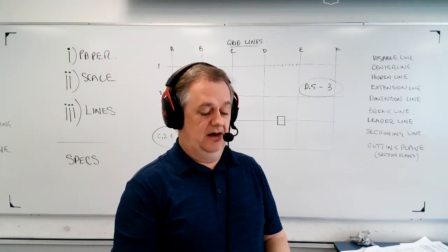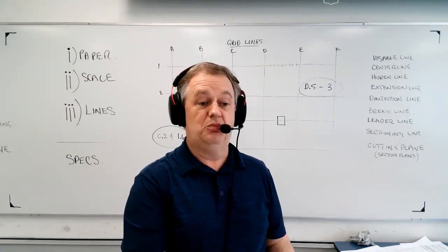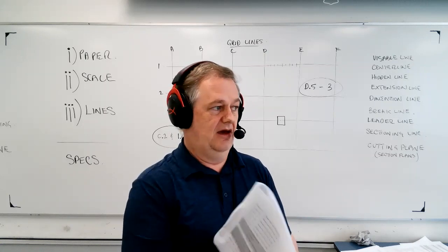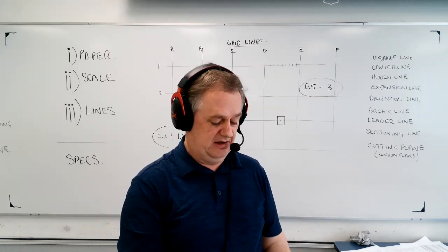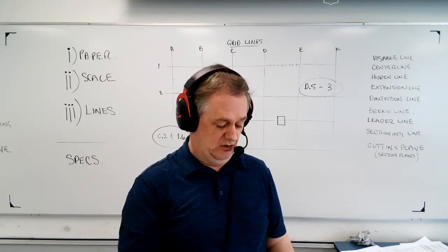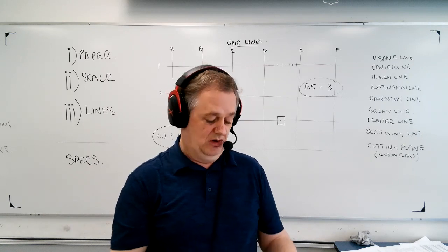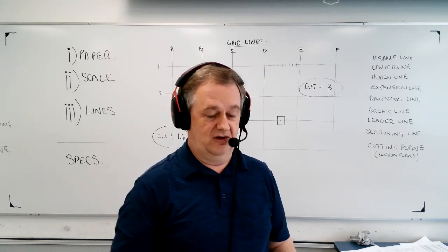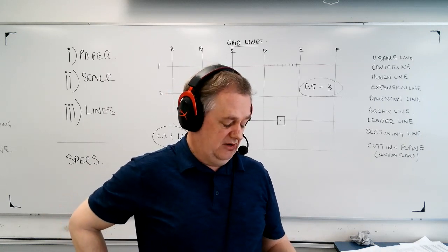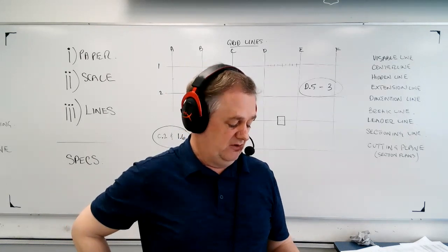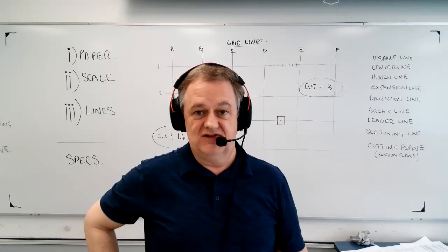This format doesn't use every section, so it's similar to code in that way. There are some that are at this point not used, and they're going to be filled in as necessary with changes in technology and equipment possibly. So you'll see 15 to 20 reserved for future use. Electrical, I think you should know what section in the specs deals with electrical equipment, and it's section 26. And if you look down to the end, there's some more reserved for future use, and it goes up to 48. So 48 different divisions in the spec.